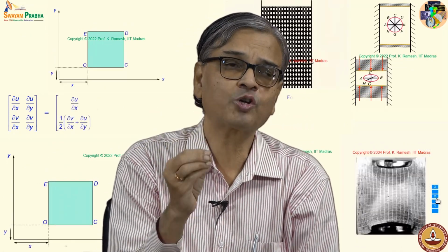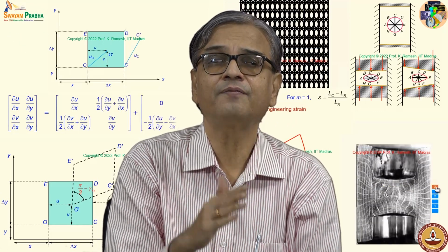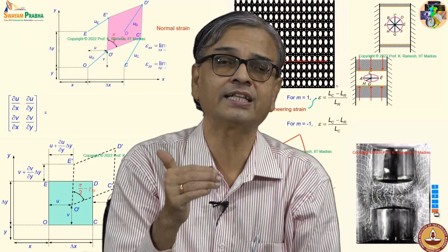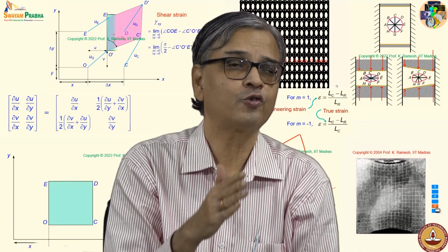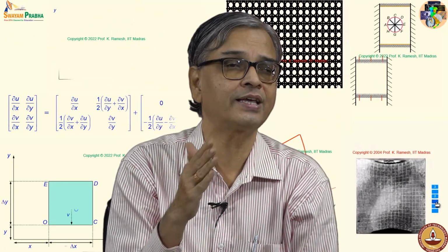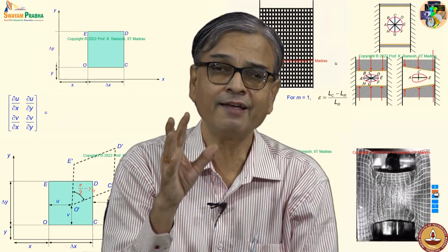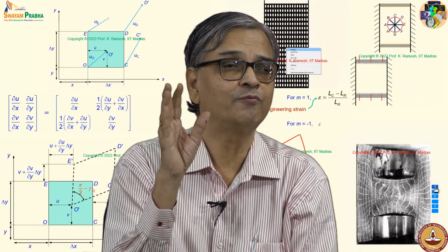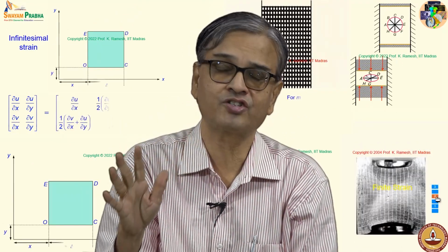Then we developed concept of state of stress at a point. Similarly, we started with change in length by original length as strain, and we have said if you have epsilon x, epsilon xy and epsilon y, it behaves like a tensorial nature, and whatever the concept that we developed for stress you can find in strain.